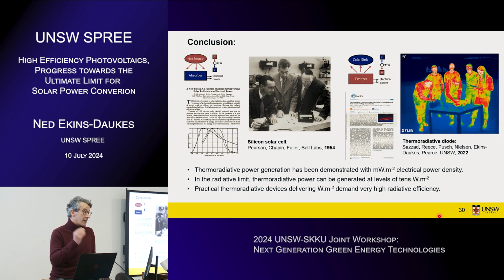So let's take that cell from Longi that's already 27%. If we make similar assumptions, that it's going to work really well, it can push it to 33%. Now, we need to be careful because if you take these thermodynamic limits, you actually end up with an answer of 42%. But that is already taking a baseline cell that's more efficient than silicon could ever be, because silicon's limited by Auger, as we discussed earlier.